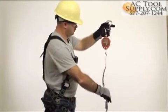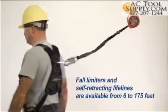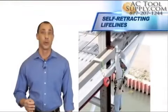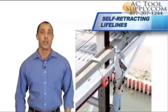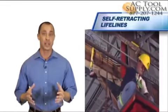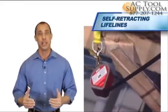Fall limiters and self-retracting lifelines are available with working lengths ranging from 6 to 175 feet. Self-retracting lifelines are durable, heavy-duty devices that have webbing or cable wound on a brake drum that extends as the worker moves away from the anchor point and retracts as he nears the anchor point.